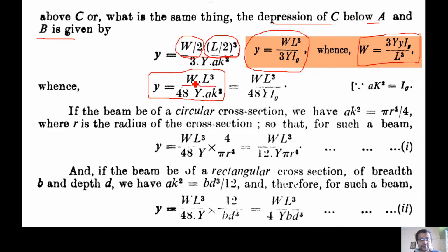That is what you can just solve mathematically, and you can get the final relation. That's how you express the depression produced when you apply the weight at the center. Just plug in the two ends of it, and you will get this particular depression produced that you calculated.